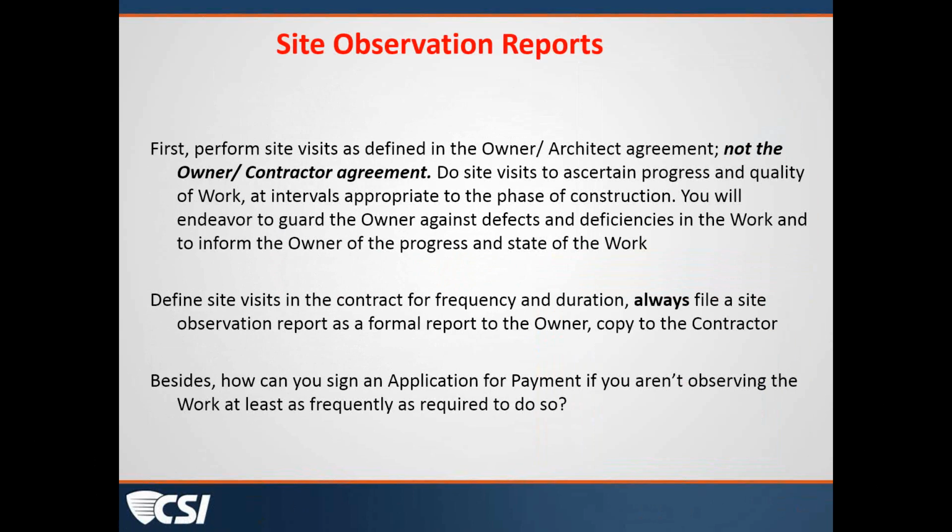So in this case, windows were submitted and they were looked at and they were approved with notations and sent back, and they were the wrong window. They were not made for a brick veneer installation. And so in the locations where there was brick veneer, it was the wrong window. In other locations that were a different perimeter construction, the window worked. There should have been other window types used for the brick veneer. So the architect didn't catch that at that moment.